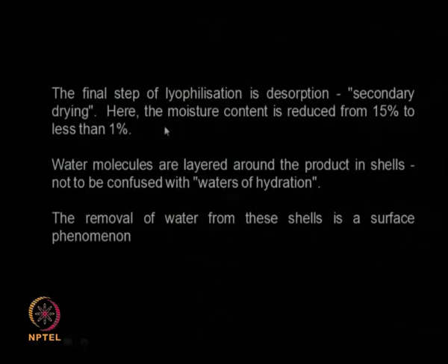There is a lot of water present on the product in the form of a shell. It is a surface phenomenon, it is not water of hydration, so you should not confuse the removal of bound moisture with removal of water of hydration. It is more like water present in the form of a shell.